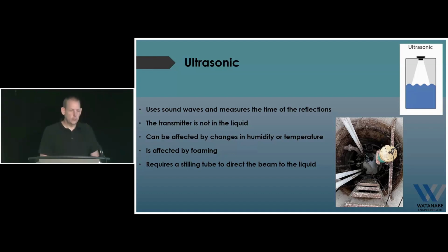These tend to not punch through foam very well because it's a slightly lower frequency pulse that it's sending down to the liquid level there. So basically the way that it works is it sends out a pulse, and it looks for how long it takes to see that pulse reflection come back up, and that's how it determines the level. And then when you get into the transmitters, there's ways of telling it to ignore things in the wet well.